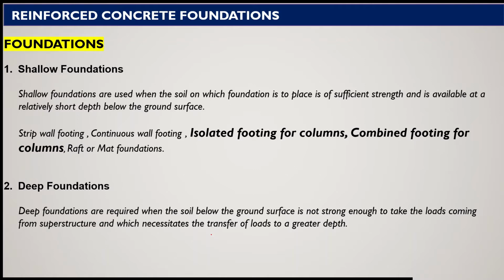So that means if the soil beneath the wall or column, whatever be the mechanism to transfer the load, is not strong, not having sufficient bearing capacity to take care of all the loads coming from the superstructure, then we have to go deeper into the soil so that we can come across a suitable soil having suitable bearing capacity, or some solid rocky material is available where we can transfer the load.